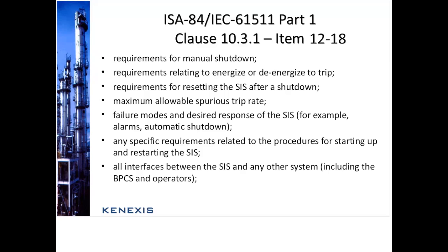We have requirements relating to energize or de-energize to trip, and the associated requirements that would follow, especially for energize to trip, potentially circuit monitoring and other things that prove that your system is going to be able to take its action when it's demanded to.